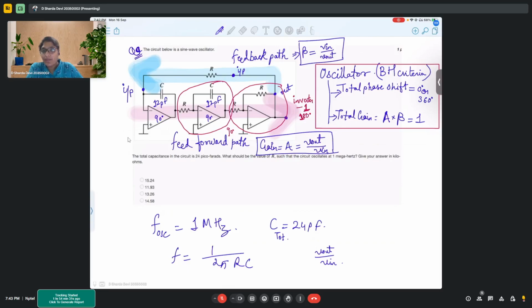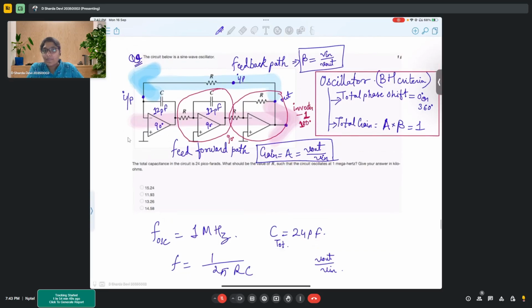Yes. So we are looking from the input side for the total capacitance. There are only two capacitors available over here. We are not talking about intrinsic capacitance. These are external capacitances that we are using. Whatever capacitance is given in this case will be external only, nothing internal. With respect to op-amp, until you go into the internal circuitry of the op-amp, we only talk about external components. Only for output impedance do we talk about internal resistance, but capacitors are always external in the case of op-amp.